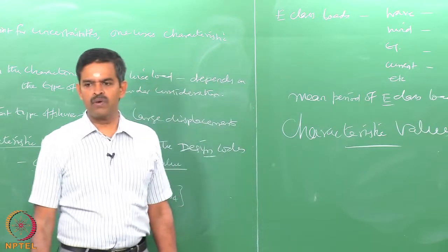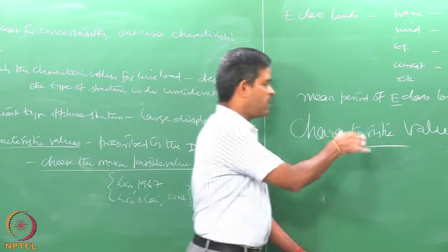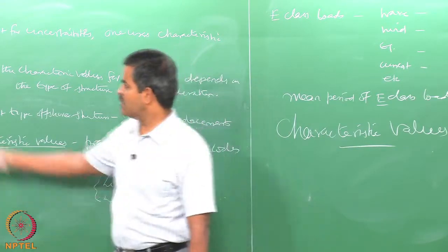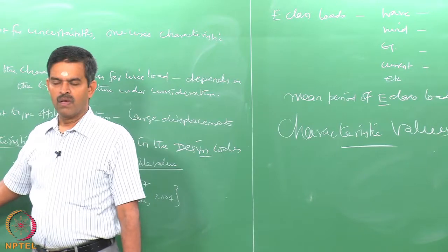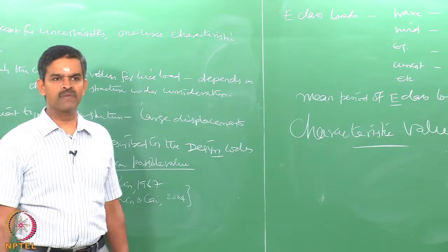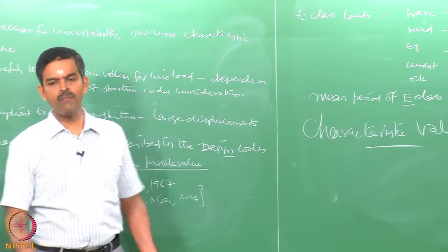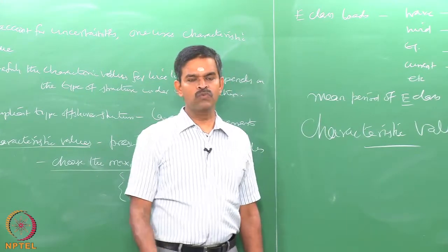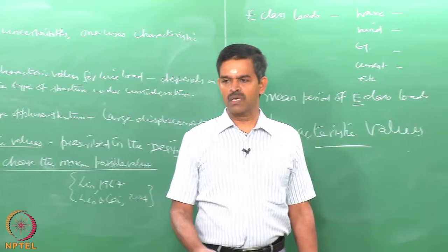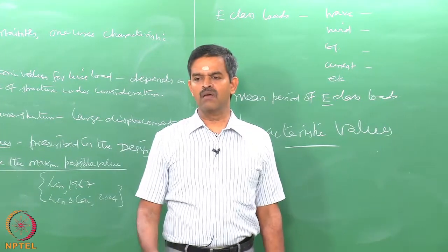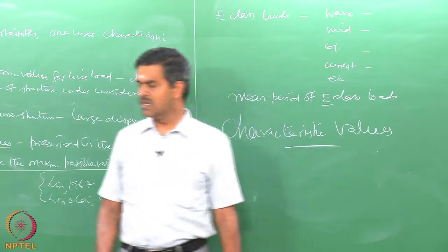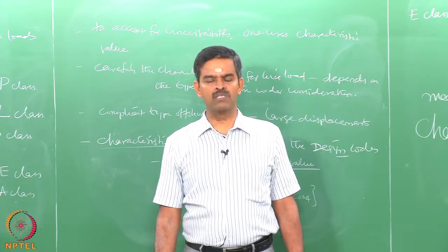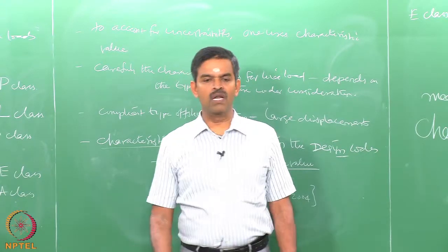Obviously, one can easily come to a conclusion that a single characteristic value cannot represent the variation uncertainty on different class of loads. However, as advocated by different researchers, one should use the maximum possible combination of characteristic value because this is useful in accounting for or representing highest degree of uncertainty which are faced by these class of loads in estimating. Now, one can ask me a question, how this will affect the reliability study?